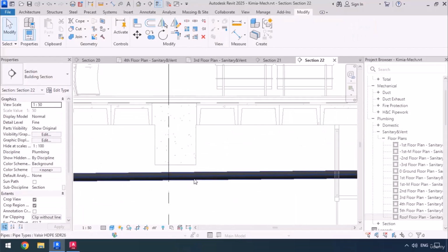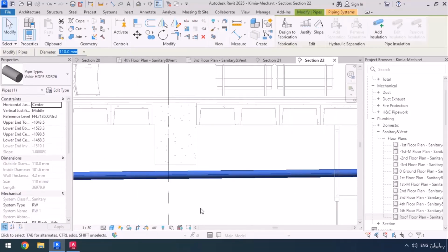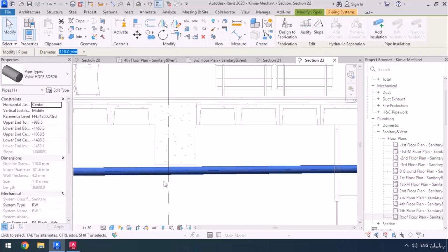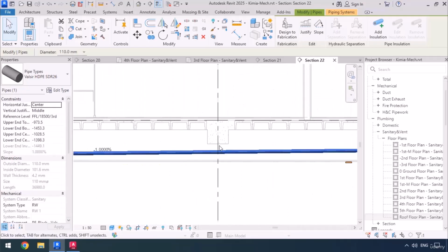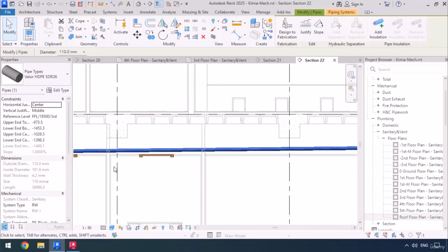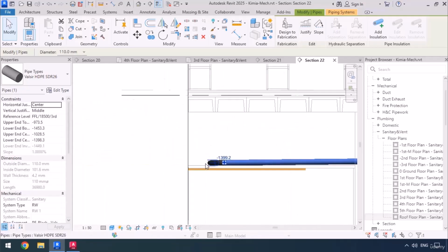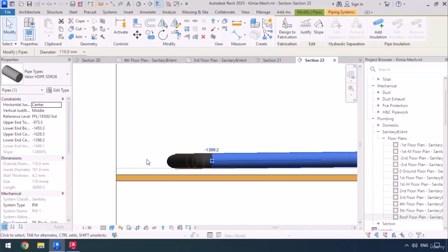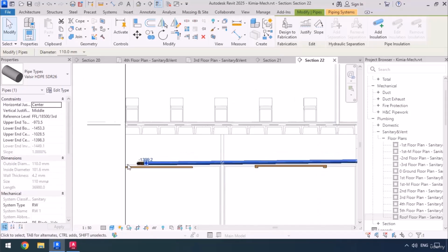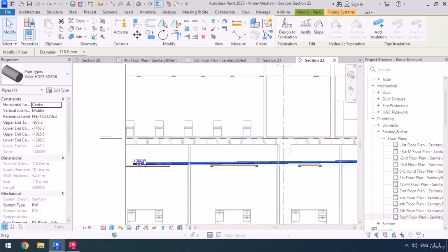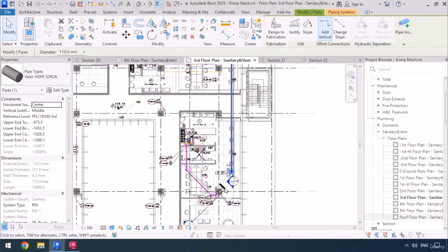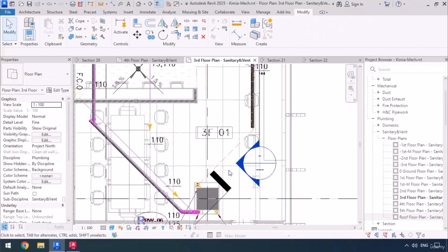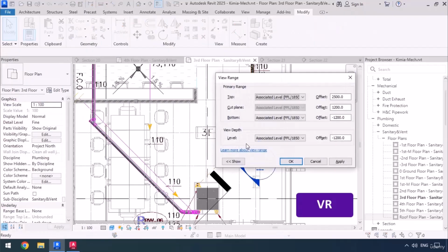Let's head into the third level and check from the beginning of the pipe. Here's the first beam, and our pipe could go higher, so we're going to select it and use the arrow keys on the keyboard to move it higher and closer to the beam. It's also going past the next beam and the next one and the next one, and then if you look over here you can see that it is almost touching the false ceiling. So basically that 1% slope that we've applied to our pipe has made it touch the false ceiling by the end, and that's kind of problematic for us.